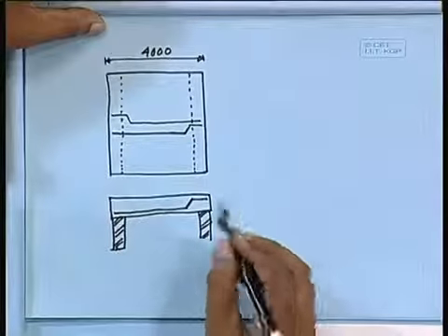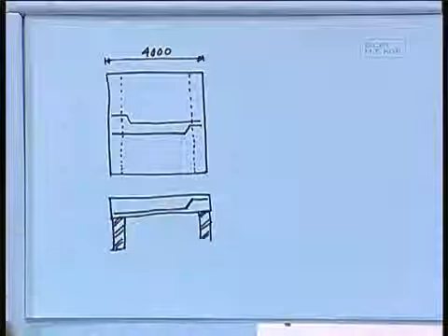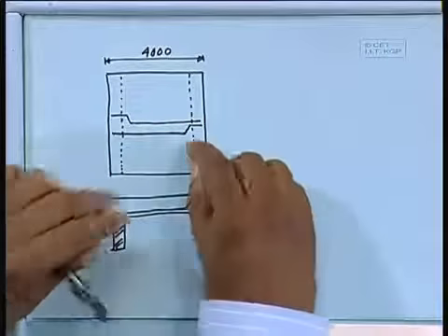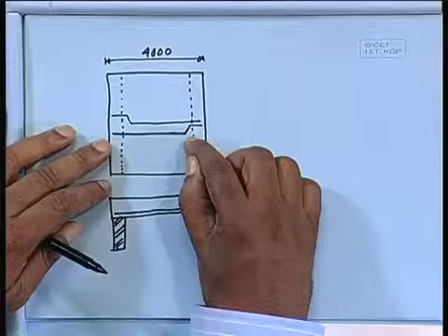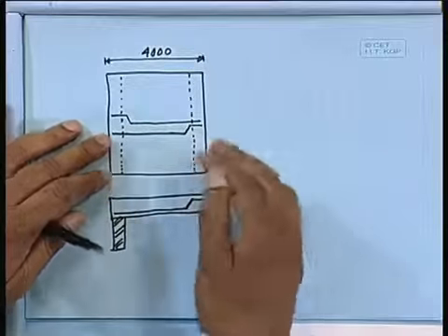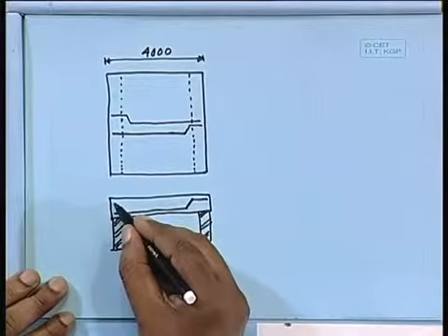That means alternate. So your reinforcement will be the same, the bars will be the same, only one will be placed this side, another one will be placed other side. So it will be cranked in one side only. At the construction site, they will crank on one side, but they will place alternately. So I shall get the other reinforcement like this.